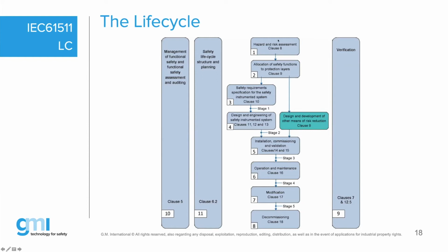frequency. Now, we will do some other sessions, or we have done some other webinars already, so here we'll be very brief. So once you have identified your hazards, you know your likelihood, you know your consequence, then you can define your risk. And your corporate management of the end user, the operating companies, the corporate model will tell you what is tolerable, what is allowed in our factory, in our company, in our industry, yes or no.